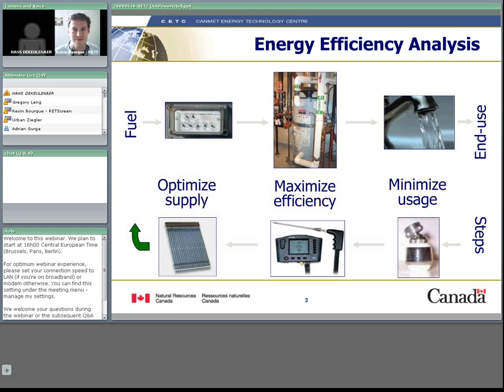So we had two options. One is we needed to replace the windows because they were very leaky, and we also needed to replace the furnace. Had we replaced the furnace first, because it's probably an easier and cheaper option, we would have sized the furnace for the existing heat load and heat loss in our building.